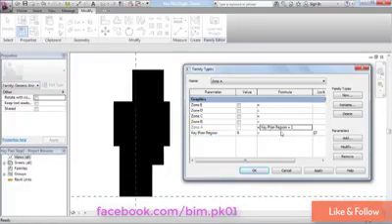Well, this is a special case of the if statement. When you do an if statement to control a checkbox, because the checkbox can only have two possibilities, checked or unchecked, you basically describe the true condition. So we say key plan region equals 1. What we're saying is if that occurs, then the answer is yes. So we want the box checked.